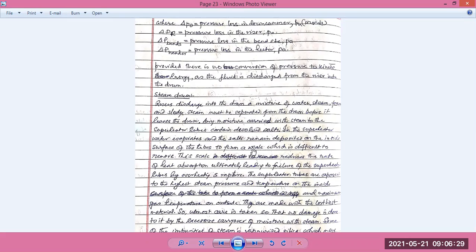The problem is that the superheater is supposed to get steam at only around 100 degrees centigrade, which is heated to superheat temperatures of around 500, 560, or 600 degrees centigrade. But with this temperature rise, salt cannot be converted; it remains as solid as ever. If it is not removed before going into the superheater, it will deposit there and create a coating over the surface of the superheater itself.